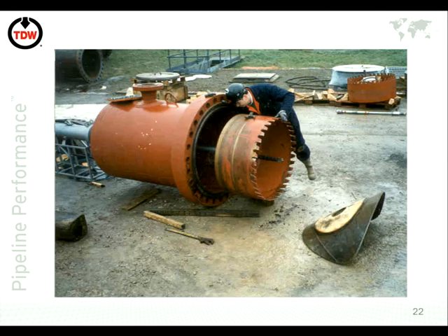That can be swept out with a pigging operation. And you will see that once you do a pigging operation. If you have had a hot tap operation on there, you will pull out bits of swarf. So getting back to your point of illegal tapping, that is something that pigging operators will look for in certain areas of the world. If they start to see swarf in there, it will give an indication that somebody's been doing something on the pipeline they shouldn't have.